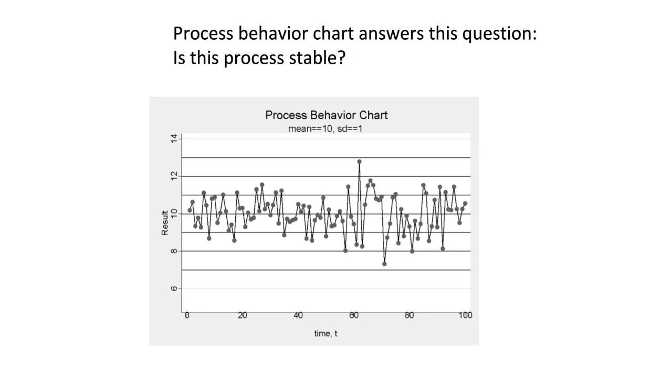In this chart, the control has a target of 10 nanograms per mil, but we see that the measurements vary around the target value over time. We use this chart to determine whether the process is behaving, quote-unquote, normally. Thus, we look for some unusual pattern in the results, and if we see one, we suspect there's a problem, and that is that the process is unstable. Thus, to use a control chart effectively, you need to be a student of variation and need to understand what causes variation in process behavior.